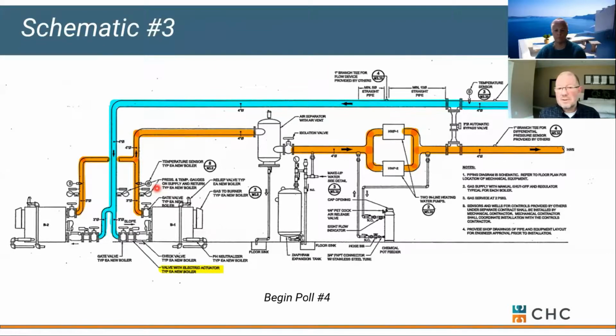The other thing that stands out on this drawing is we've got a weird bypass in the mechanical room. Now, this particular engineer doesn't design around 3-way valves in the system. Only wants 2 ways out in the system. So when they all go closed, there's a potential for no flow in the system. That's bad for the boilers, bad for the system pumps.